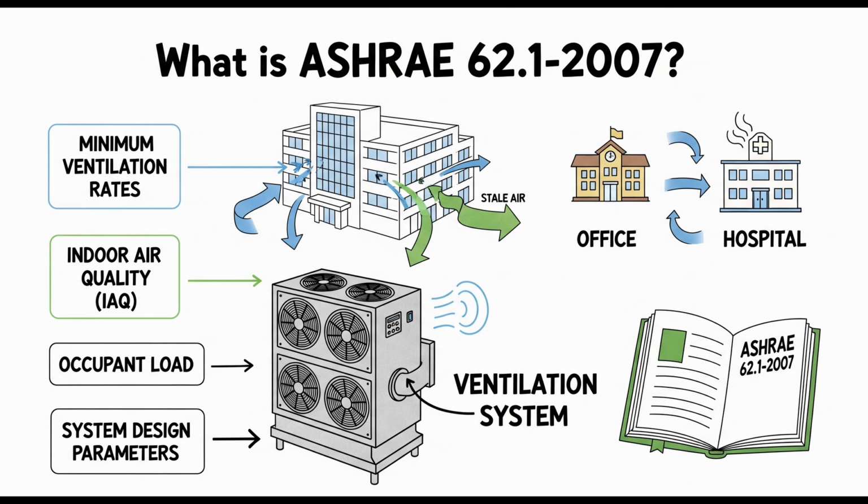Okay. The standard requires particulate filters upstream of any wetted surfaces, like cooling coils. And the minimum efficiency is specified using the MERV rating. It has to be MERV 6 or higher. MERV, what's that stand for? Minimum efficiency reporting value. It's just a standard way to rate how well an air filter catches particles of different sizes. MERV 6 is relatively basic filtration, good for catching larger dust, lint, that kind of thing.